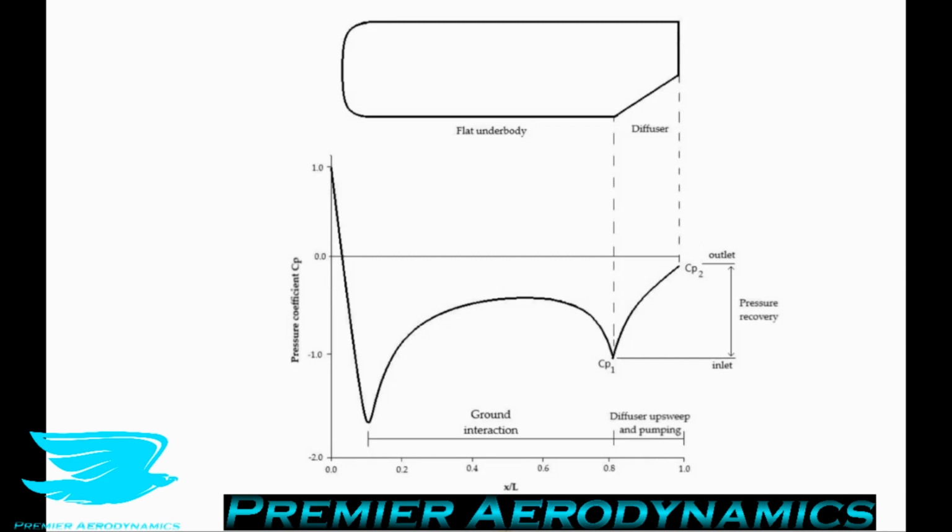But if you put a diffuser on there, now you effectively have a cambered surface when you think about it, because if you were to draw a line halfway between the one surface and the other surface, so the top surface and the bottom surface, it'd be right in the middle of the body until you get to the diffuser, and then it'll start to jump up a little bit. So that's the camber line effectively. So that means that there is camber to this object. And if you have negative camber, it means you're going to get more downforce. So that's what they mean here.